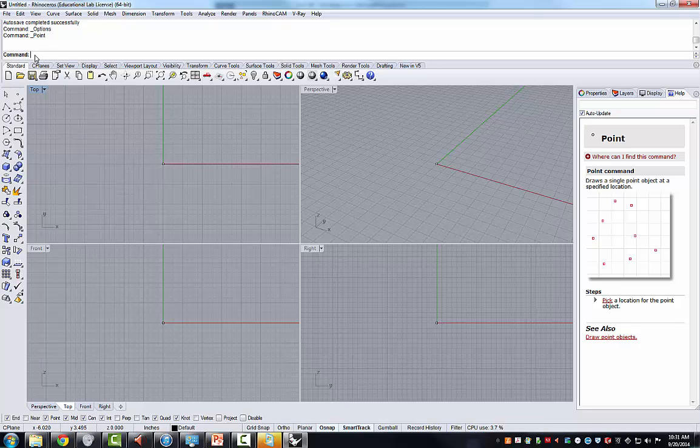This area is also a place where you can simply type the name of a command. So I can, for instance, type the word line. A series of possibilities pops up. So I can choose line, linear, light, anything that contains the 4 characters LINE, polyline, etc., curve through polyline. They pop up with the most often used and the most expected response as the top one.